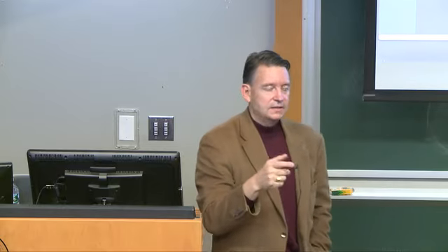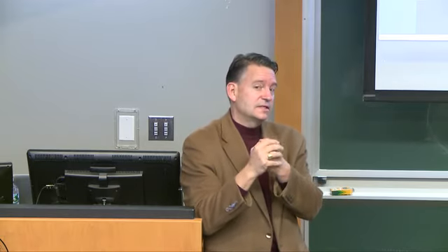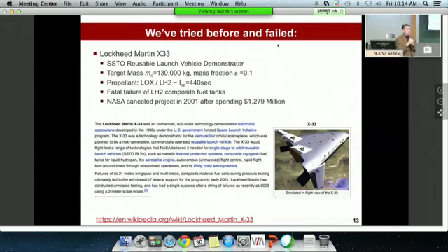I was wondering about the mass fraction. So I read the text over there, and it says it's suborbital. So was the plan to even reduce that mass fraction further if this was a success? Right. So this would not have achieved orbital velocity, and it's not a complete one-to-one map because I gave you a higher delta v. I gave you 11 kilometers per second, which is escape velocity, and you really need to achieve about 7.5. But with drag and gravity losses, you really need to achieve about 9.5. So it's not a one-to-one map, but you sort of get the idea.